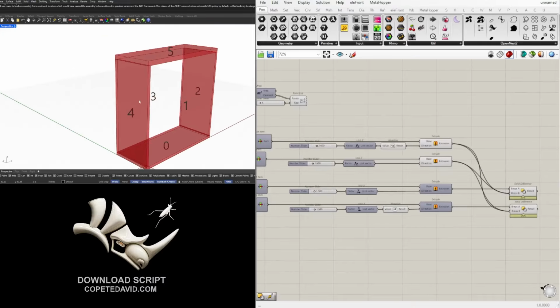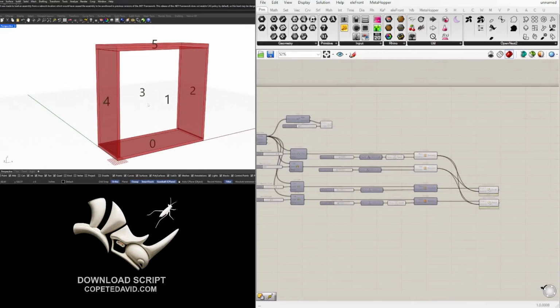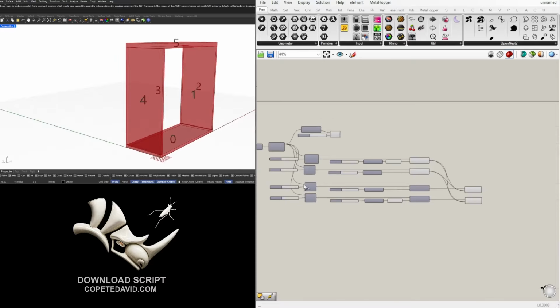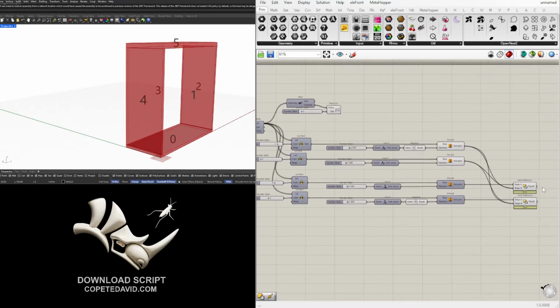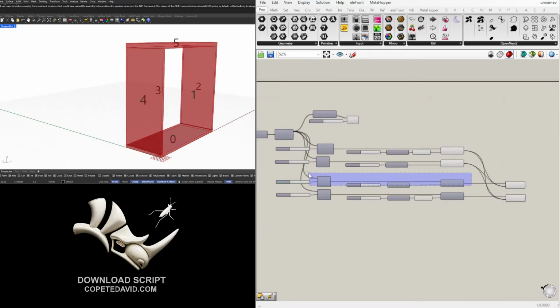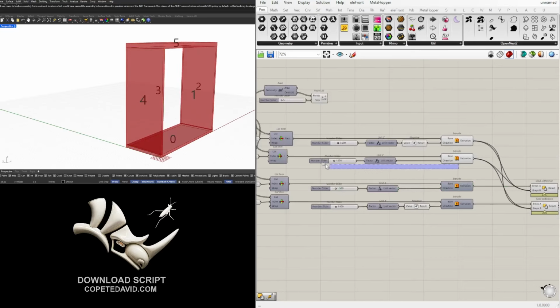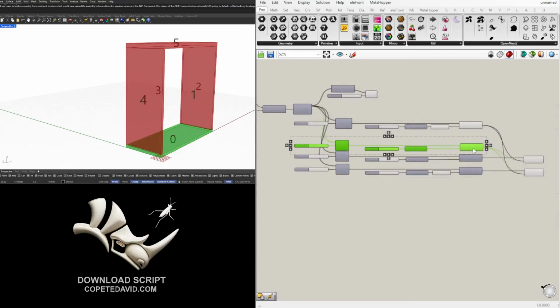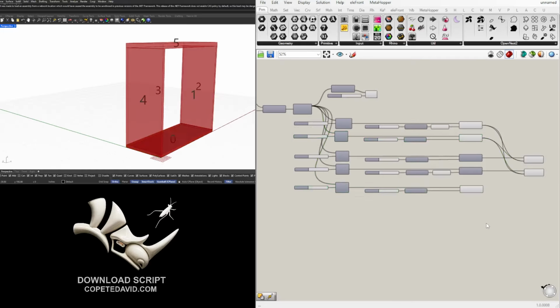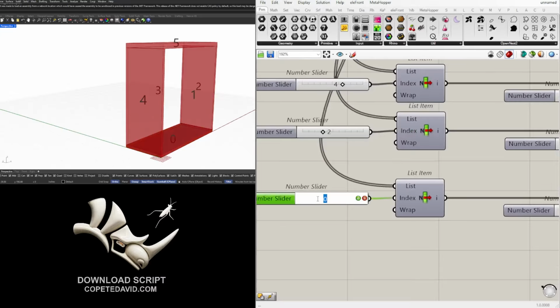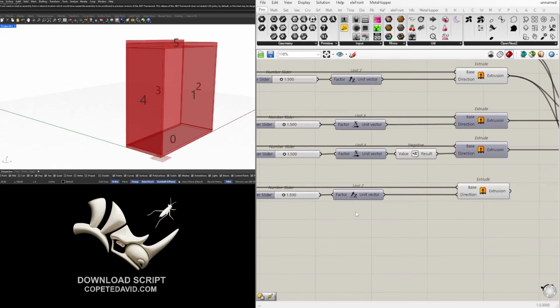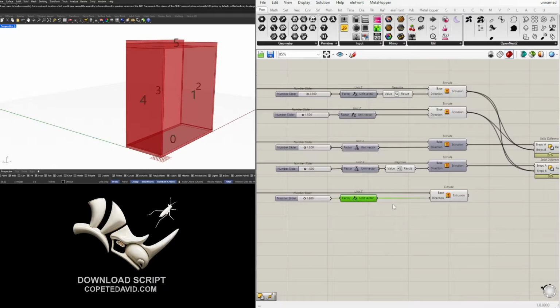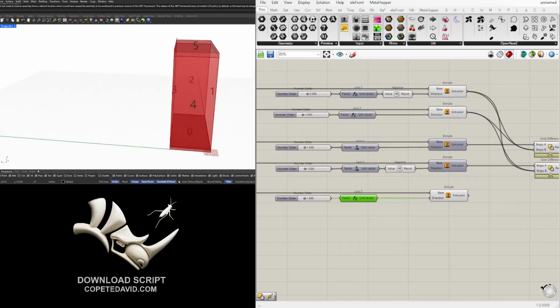And now lastly, I think we need to bring in the back face. So that's surface number 3. And so we can take this. Well, we'll take this. Actually, this one. You can pick any one of them. Just this one is already previewed. Slide it down, tap Alt. Go here to number 3, which is the back panel. And instead of extruding it in the Z direction, it's going to be in the Y negative direction.